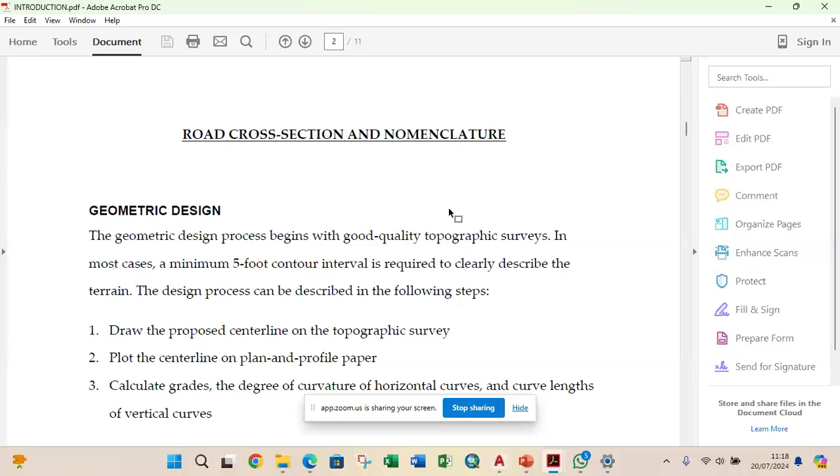For the Federal Highway Manual, they've done their research, just like I was saying, on the annual daily traffic, and come up with a minimum carriageway for a federal road of 7.3 meters: 3.6, 3.6. Then the axial loading you're talking about comes in when you are doing your pavement structure and pavement analysis design, that is, your subgrade, sub-base, base course, the wearing course and the asphalt. So that's the axial loading they are talking about.